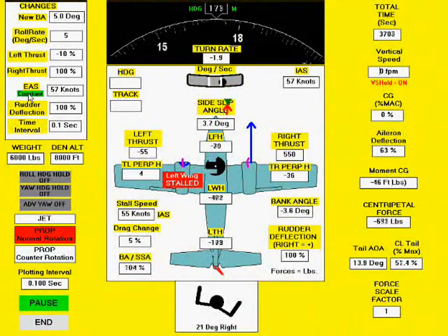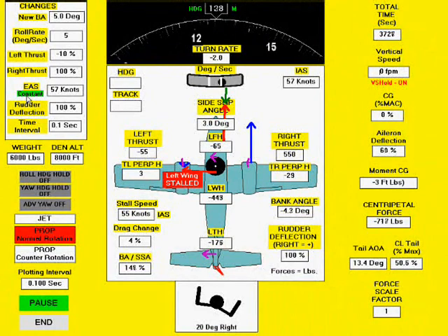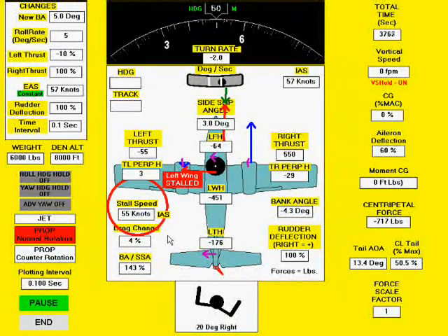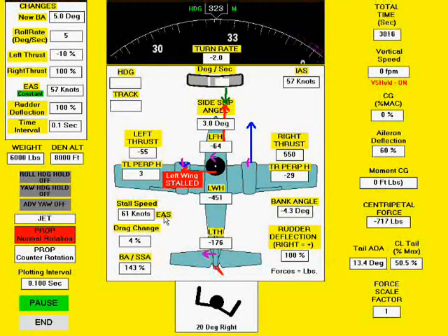What happened? We are apparently above our previously observed stall speed of 55 knots, but stalled before reaching full rudder deflection. The problem is that VMC is lower at high density altitudes, and indicated airspeed can be significantly inaccurate at high angles of attack. The correct stall speed in this case is 61 knots.